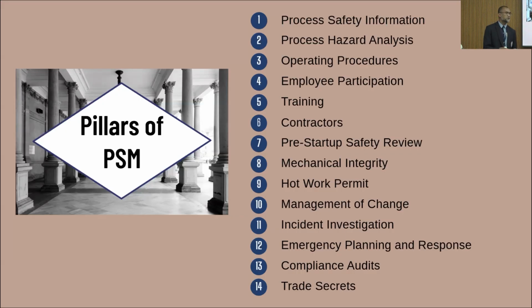Operating procedures: you ladies and gentlemen might be familiar with the process, but at some point you will be supervising people who aren't. You have to write operating procedures. As part of the operating procedures, you have to make sure that safety considerations are included. Employee participation: there is no point talking about PSM here in this room if the employees don't know what it is and are not interested. So you need to get your employees engaged as well.